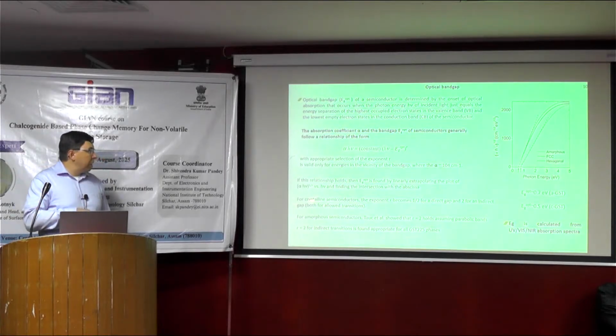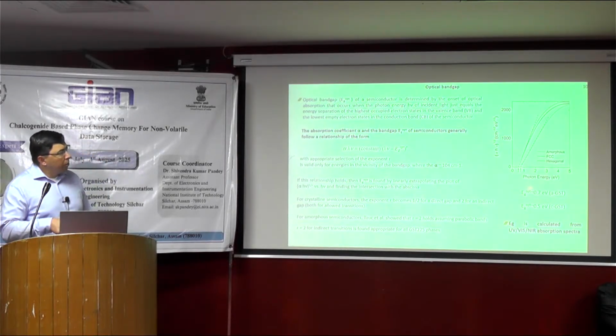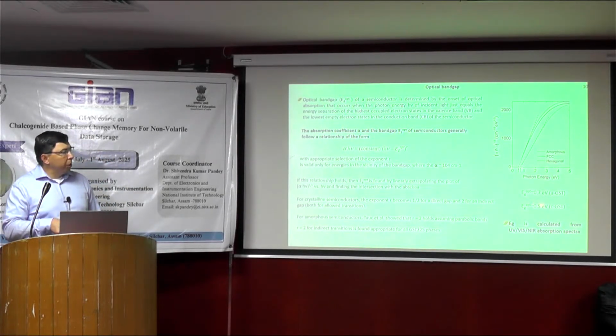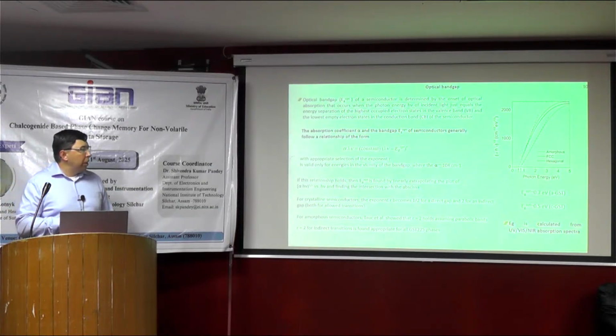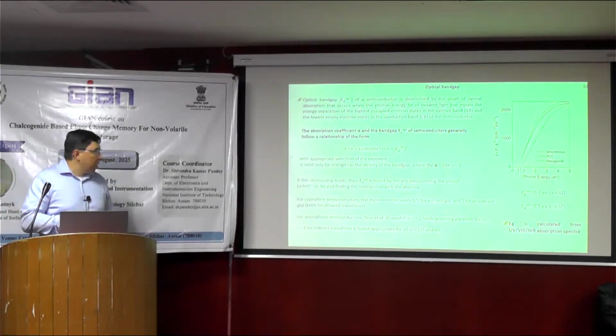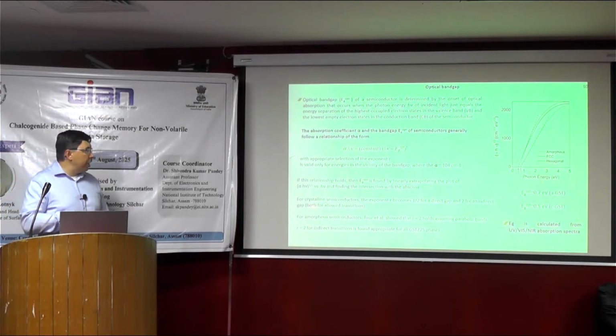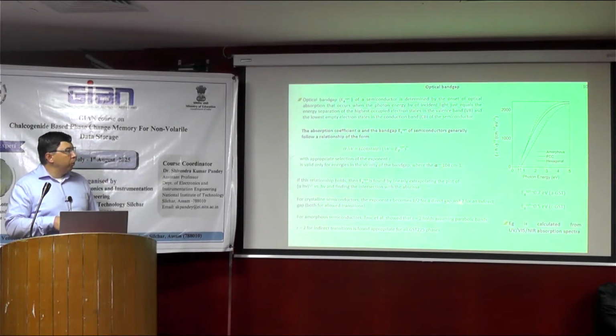For crystalline and for amorphous GST, the band gap is around 0.7 eV, and for CGST, this is a little bit lower, 0.5 eV. Now to this R, or N: you find the exponent for crystalline semiconductors. This exponent is one half for a direct gap and 2 for an indirect gap.